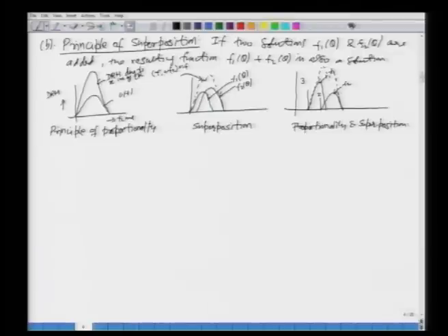So, this is again your F equal to, maybe I can say 3 times I1 plus 2 times I2, which is applied on your F, where I1 is the response due to the unit hydrograph at that particular time, and I2 is the response due to the second impulse. All right. So, this way we see that we can apply the principle of proportionality and superposition to solve very simple or sometimes complex problems. Okay.